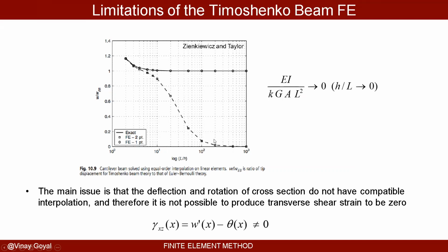But if I reduce the number of integration points to 1, something very miraculous happened. And that's that I get a really close solution to beam theory. Timoshenko approaches the Euler-Bernoulli beam theory really well, which is very strange because I told you earlier I need a 2-point integration scheme to get there.